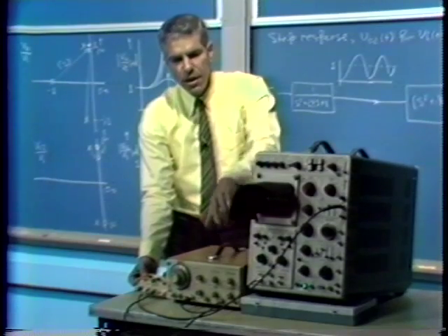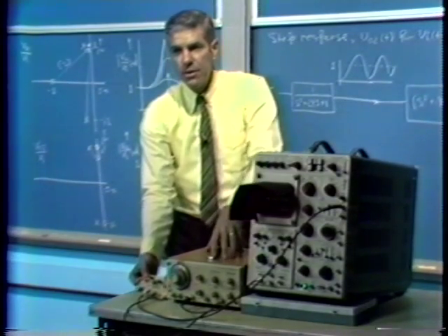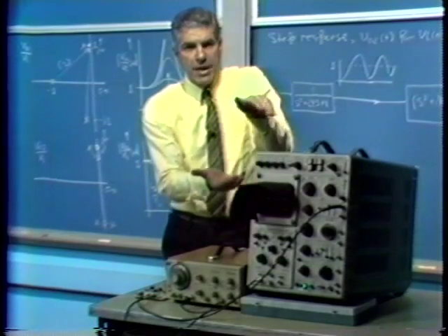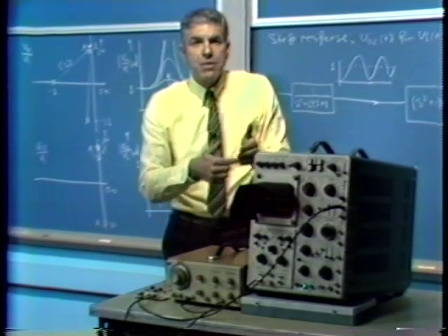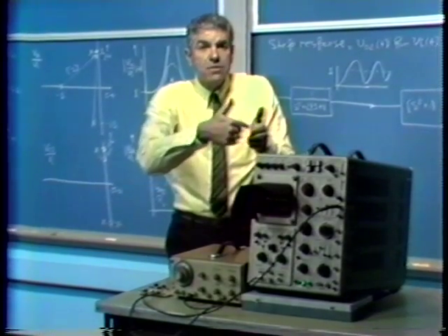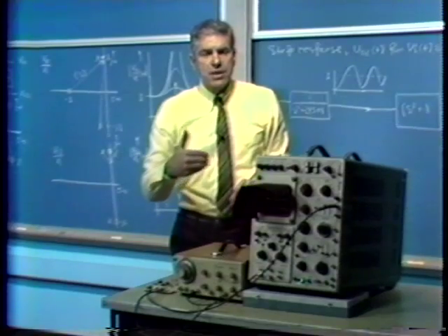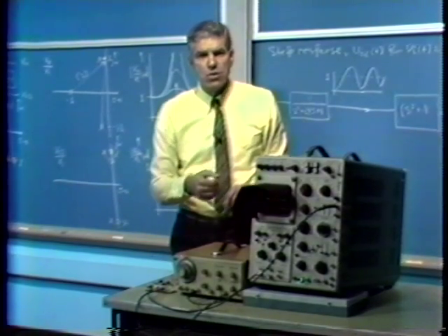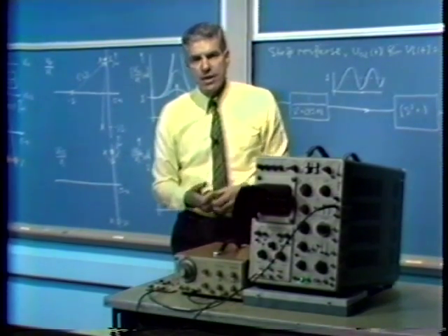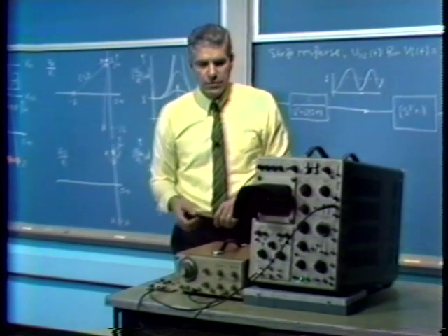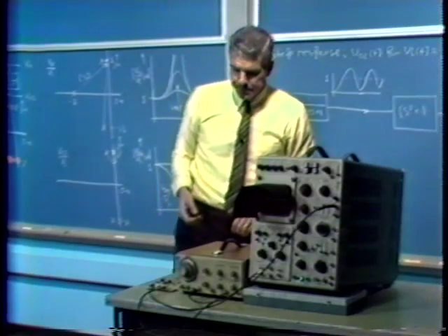So what we'll see in the oscilloscope presentation is simply an envelope that includes both the positive and negative portions. What's really happening is the carrier is running along inside this envelope, and we just see the outline of the envelope. We do a single sweep, which we store on a storage scope. The generator then retraces. So we'll look at single swept measurements of the frequency response.